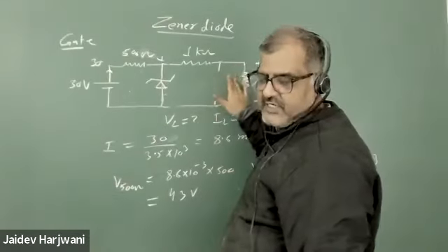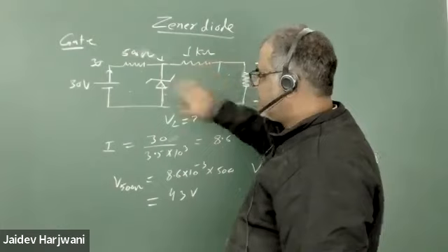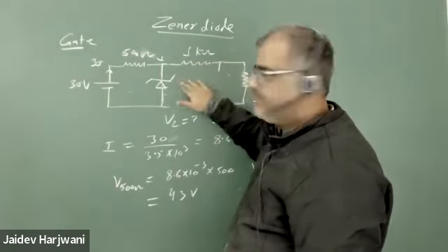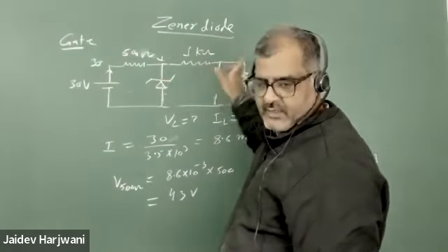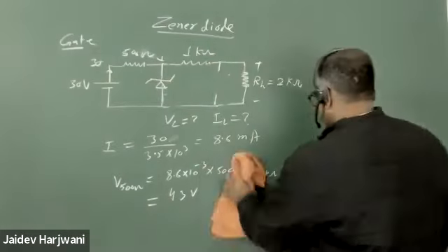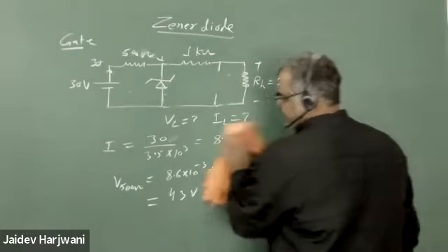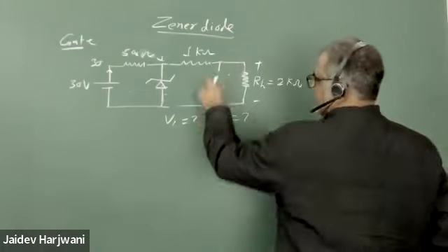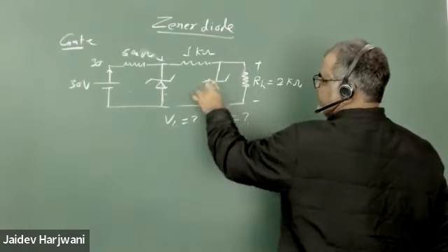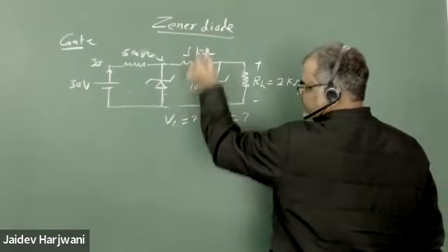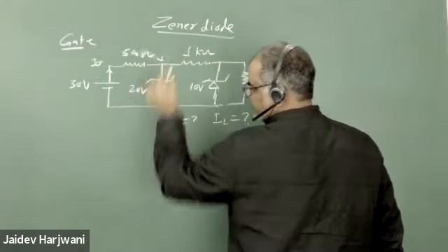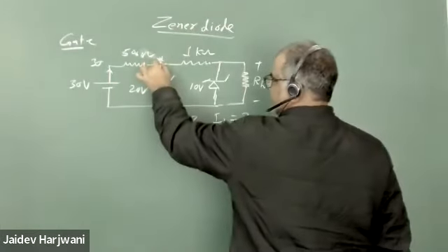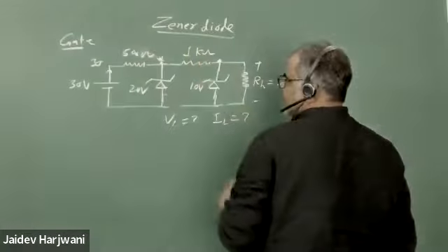So both the diodes are in working condition. I have opened both and checked. You can check both: disconnecting this one, not connecting, connecting this one, not connecting, and you can find the voltage here. You will find that in this particular case both the diodes are in working condition. Are you getting what I'm saying? Because this requires only 10 volts, this requires only 20 volts, and the voltage here is greater than 20, and here it is greater than 10.